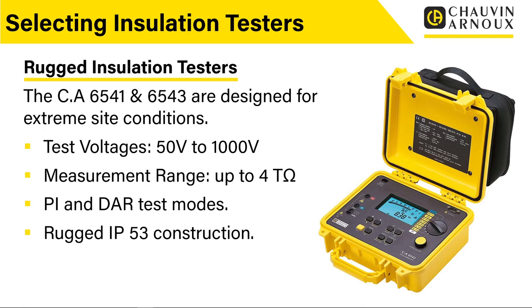These are designed to be knocked about, rugged, and used out in the field particularly. But they are also very reliable insulation resistance testers. And you can see on here that they've got the ability to test from 50 volts all the way up to 1,000 volts. So that's the range that you would expect, and we've been talking about during this webinar.